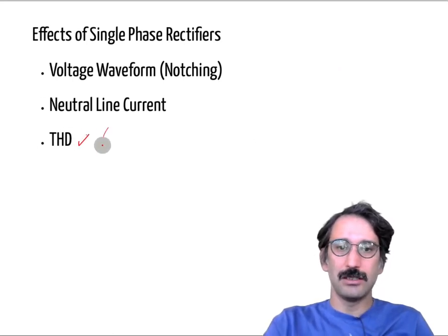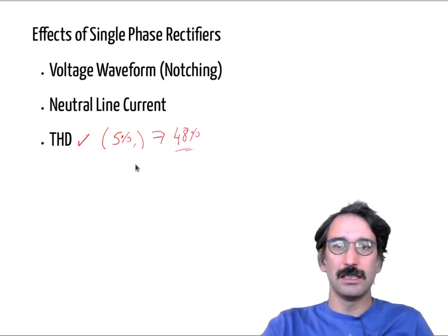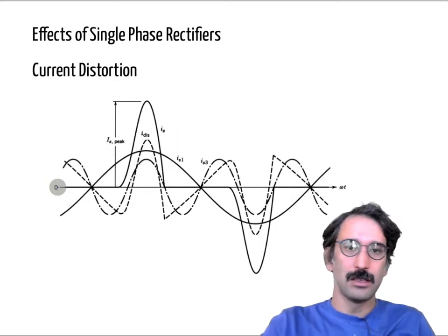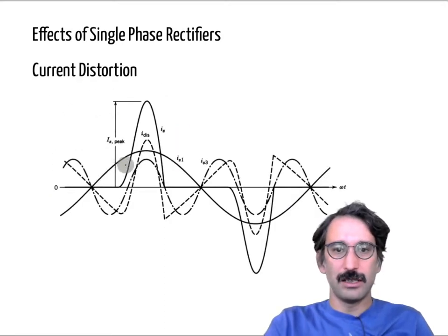Remember, the THD is usually limited to 5%, 8%, whatever, and the THD of the square waveform was 48 something percent, and that is why, if you have a high THD, then it will create some problems in your grid. So this is a more realistic case.